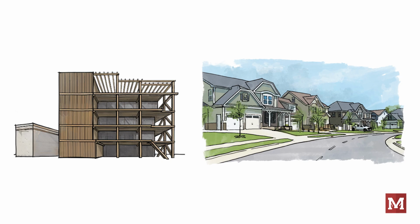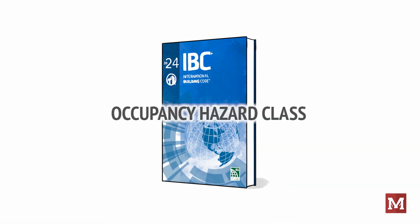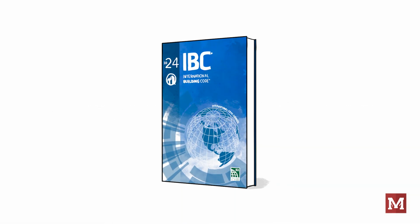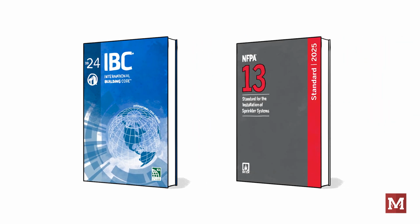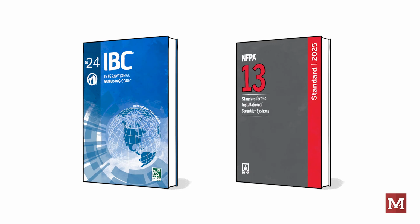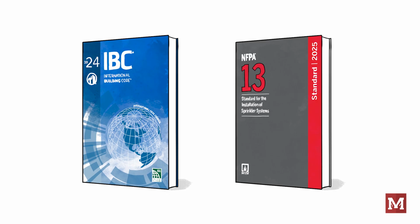This is that important. Occupancy hazard class. If you've ever done anything with fire alarm systems, you're at least somewhat familiar with the occupancy as it relates to the building code. In automatic sprinkler design, what's most important to me is the occupancy hazard class from NFPA 13. We find this in 2025 NFPA 13, Chapter 19. In prior editions, this was located in Chapter 5. This is where we determine the design criteria and design density for the system. This tells us how much water we need to discharge to control or suppress a fire occurring in the system area.